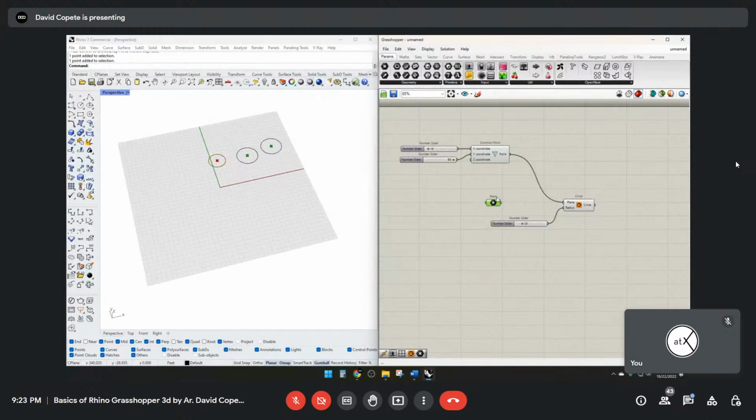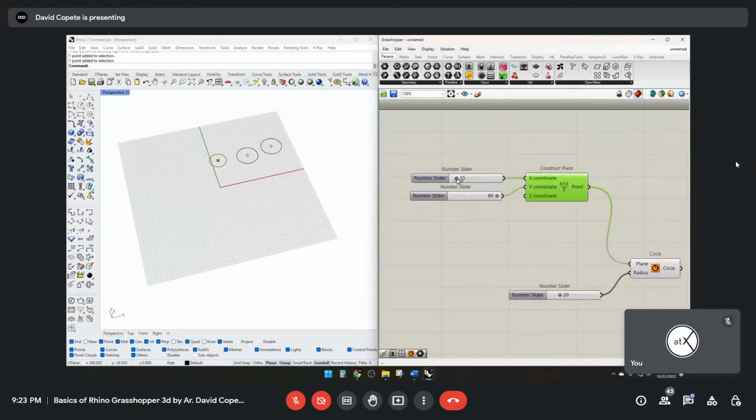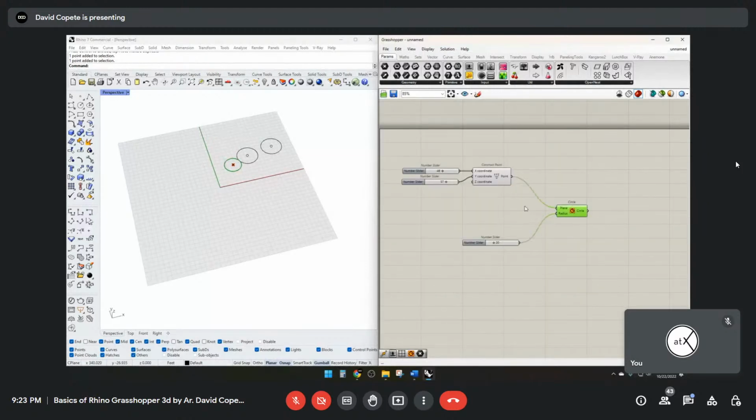Depending on how many inputs you have, you will also create more geometry. So right now it's only 1 point that this moves around. But if I wanted to create another point, well, we'll take this, I'll slide this down and tap Alt to create a copy. That's the quick way of doing that.